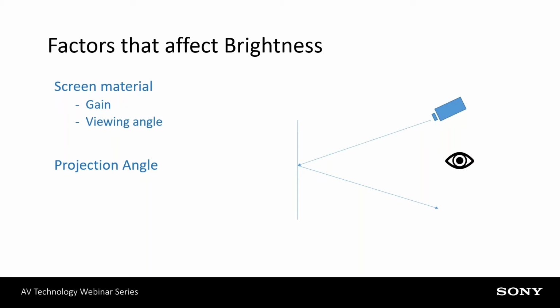So the point of this is, if you are looking at a projector and you think 5,000 lumens is good enough, it's going to be close, but that's probably adequate and so forth. You've got to take into account these other factors because, yeah, it might be adequate on a perfect installation, but when you get into a real-world installation, suddenly it's not quite adequate. And unfortunately, a lot of times by the time you get to that point to realize that, it's too late. So these kinds of factors really need to be considered when doing a projector installation.